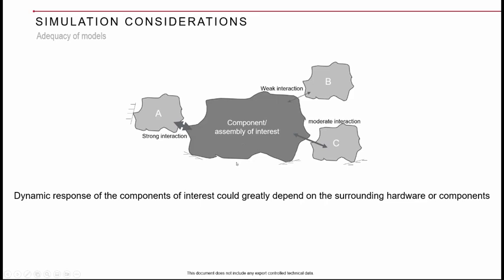when there is a stronger mode of the component of interest, the mounting unions of the tube can undergo a severe load because the tube is resisting the movement of the component, which if you don't capture adequately, you will miss that behavior. Finally, when you only deal with your component of interest, you will find that things are fine.